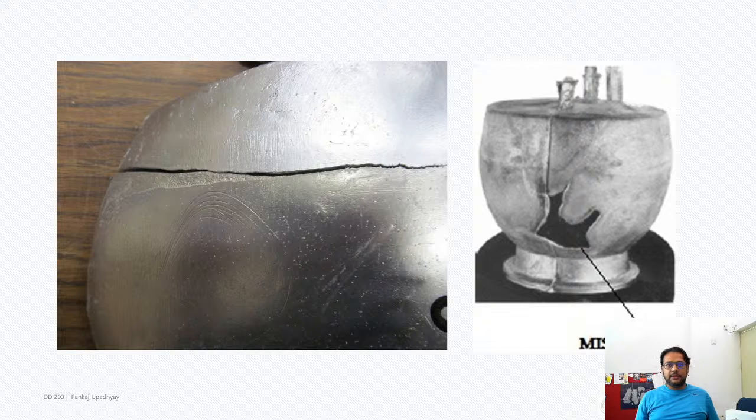It certainly isn't like injection molding. Okay, we'll not compare it to that. Let's compare it to something like machining. It's fairly high output considering machining. It can be done, and things like die casting are even higher output because you're not dealing with a temporary mold. In sand casting you are dealing with temporary molds, but in die casting you are dealing with permanent molds.